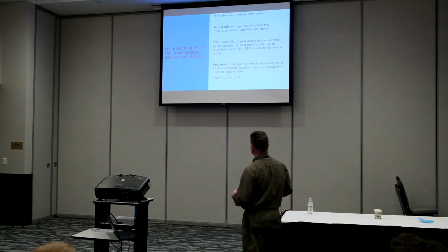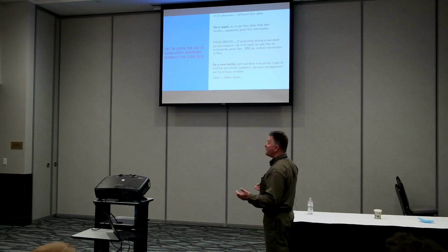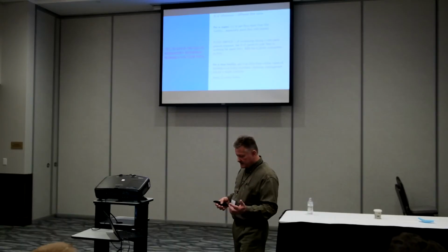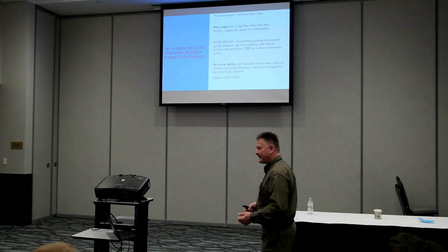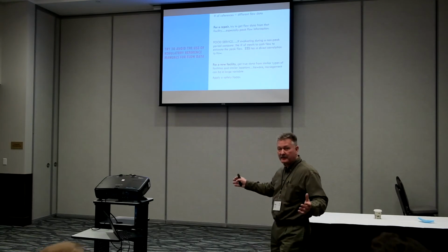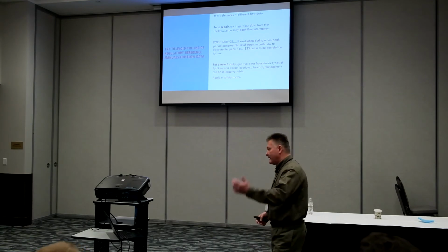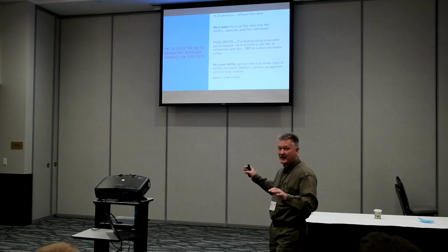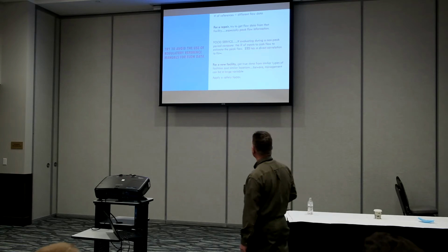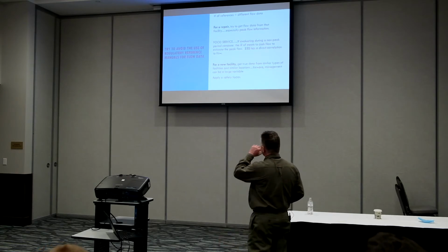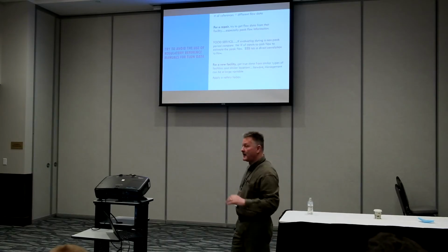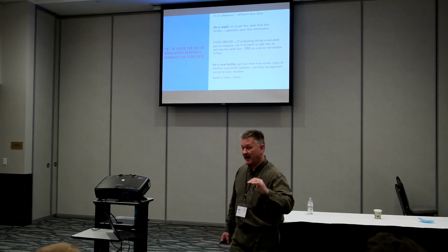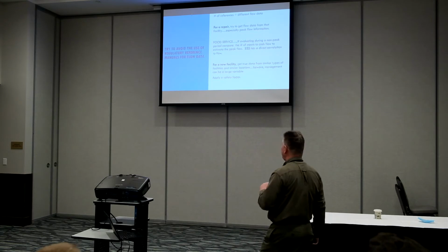So for a repair situation, try to get flow data from that particular facility. Obviously if they have an existing system, they have a failure, again, we want to mitigate any kind of health threat and so forth. And a lot of times we just automatically put them on pump and haul. Well, that can kind of skew our numbers when we're trying to design a replacement system. So food service, and again, when we're doing a repair, we want to capture those peak flows. We don't want to just pay attention to our average daily flow. We want to pay attention to peaks.